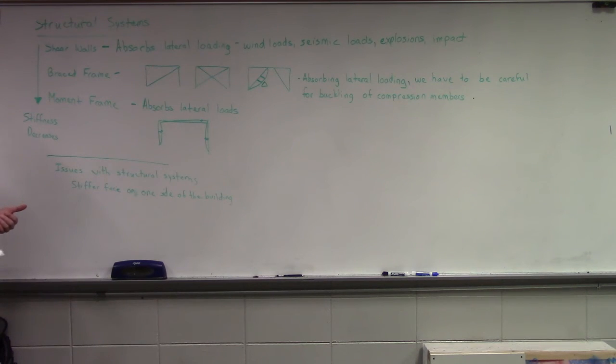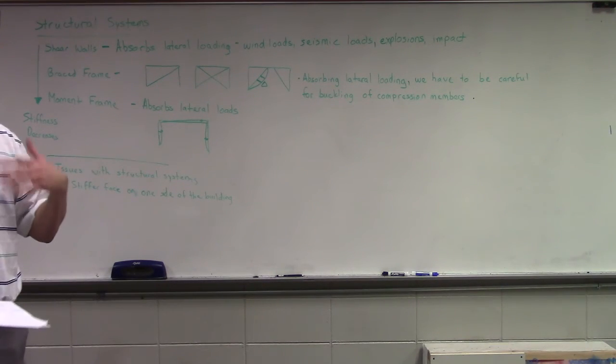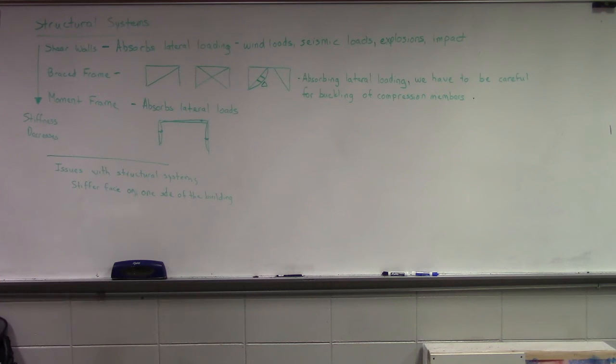You could have cracks, right? Separation. Yep, we could get into issues with our interior finishes. We could get into issues of if we have to separate material types, we could have problems with our expansion joints. So it gets back to that age-old problem of as these buildings are moving at different rates, what's going on with them? If we're making this out of CMU, maybe we're cracking the joints, right?